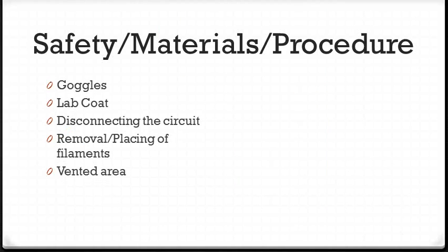For safety, I had to ensure that I wore goggles because of the filaments being burned inside the glass bulb. I needed to make sure that the filaments would not pop so hard as to break the glass jar, which would cause shattering. I used a lab coat to ensure that materials would not fall on my clothes and ruin them. Disconnecting the circuit was critical because I was not going to be touching live wires while it was connected. Also, when connecting and disconnecting the filaments, I needed to handle them with care because the alligator clips would get hot after having an electrical current flowing through them.